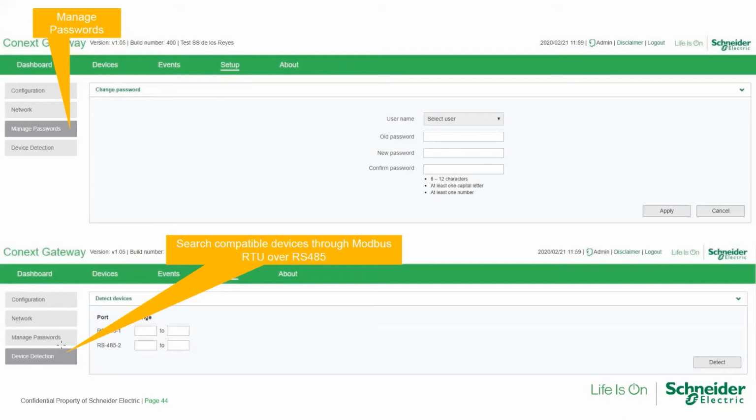So typically, if we have a system that is AC coupled and has a battery, and the battery has to communicate to the gateway, we will be using both the RS-485 1 and RS-485 2. We'll be connecting our battery master controller or master battery to the RS-485 2, for example, and we'll be connecting our DC chain of string inverters to RS-485 1.